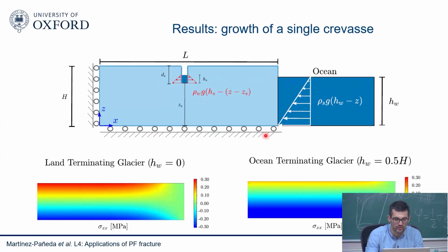So this is just a load here that depends on the ocean. And then what you have, so this is a compressive load that is closing the crack. The ocean actually doesn't want you to crack your ice sheet. However, the meltwater that you have here is applying a pressure, so you get some tensile stresses in the tip of your crevasse due to the meltwater. So it's a competition. And you can see here the stress field, right?